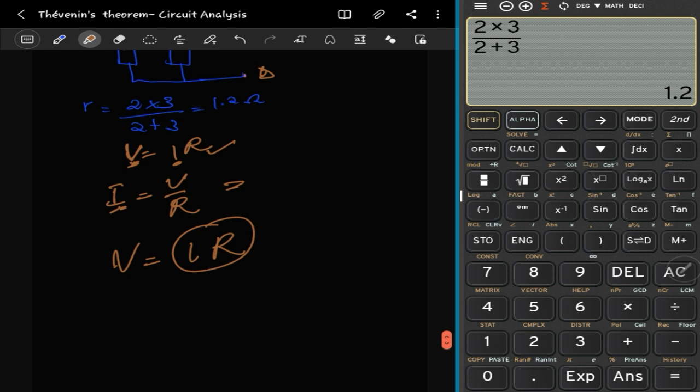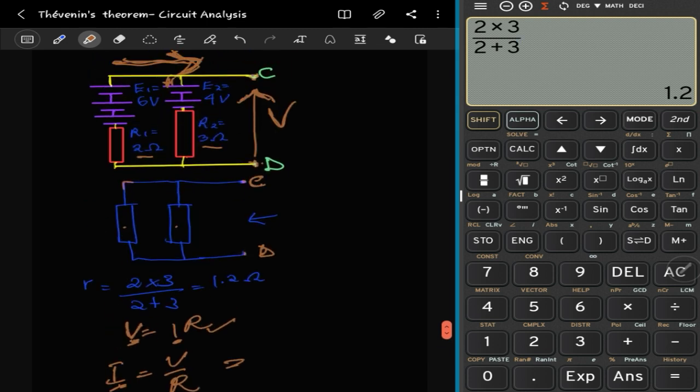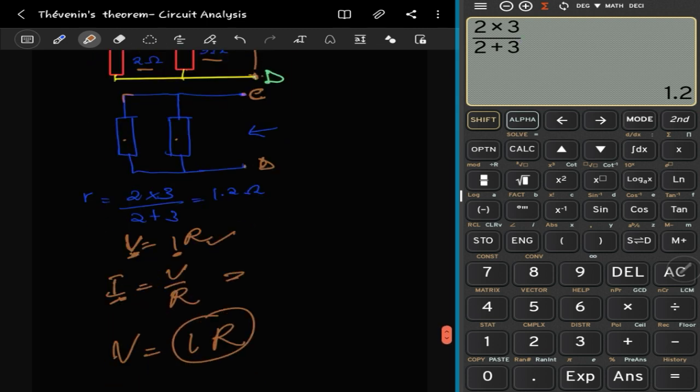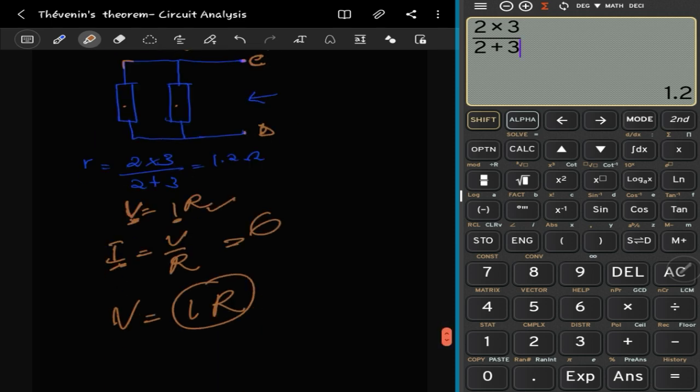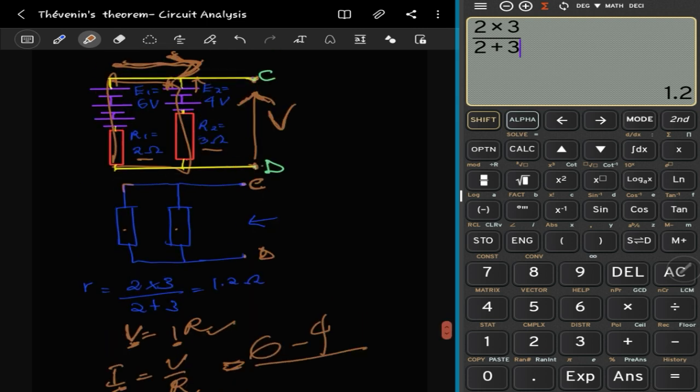Okay, so get to calculation. So the v here, which one is having this direction? This 6. So that one is positive, right? The other v, then again, you are considering this loop within the circuit. The other voltage source is this v, but this one goes in this direction, which is opposite to this one, so negative, right? So minus 4. Now we look at the resistance.